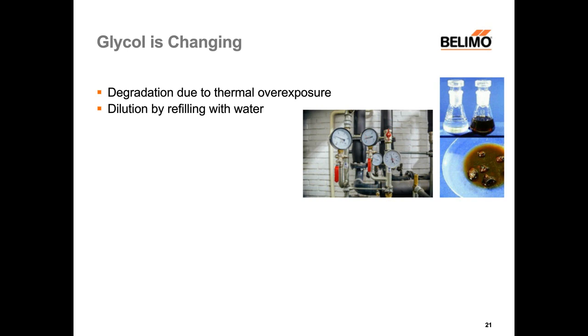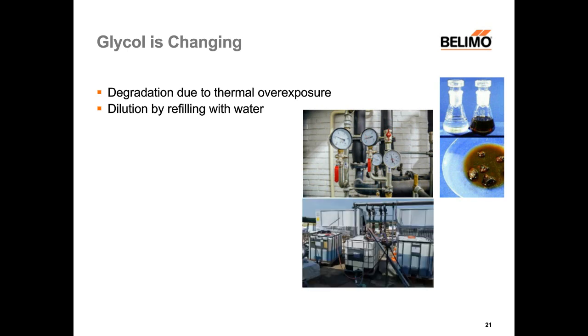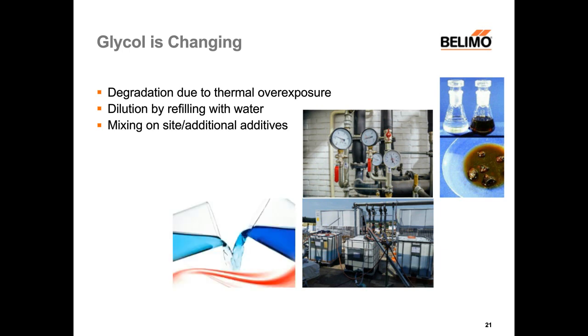Another topic is mixing on site. Usually, the instruments used to measure the concentration are not very precise, and to be on the safe side, people tend to use too much glycol, so they use a too high concentration. Sometimes they also add further additives with unknown effect. Last, also the fluid manufacturers can do changes. They can change their recipe, either to optimize their cost or because there are new environmental laws on the ingredients. So for example, a Dowcal from 2008 might not be the same as a Dowcal from 2020, even if the name is the same.